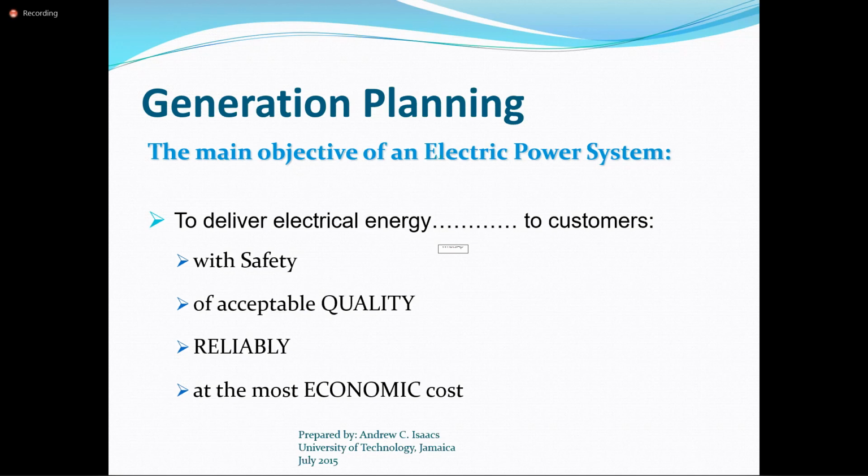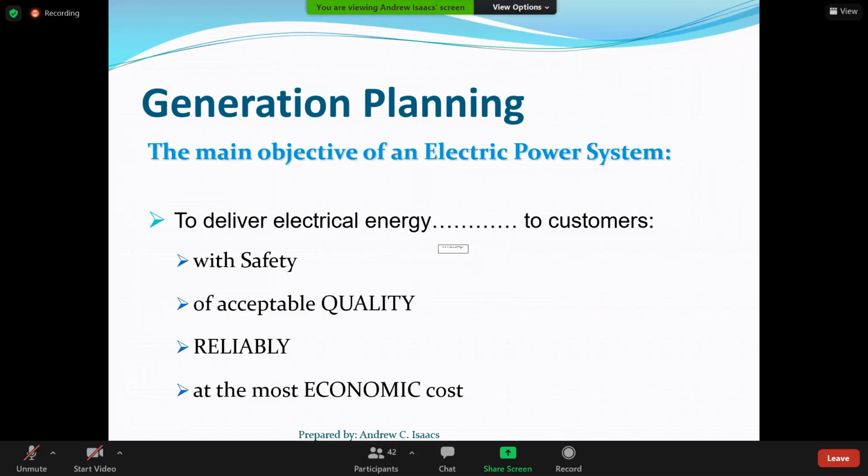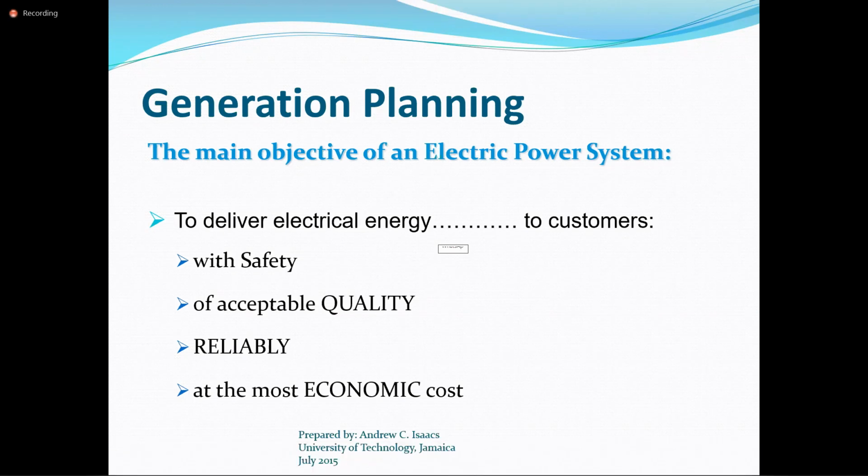And so if you have, for example, a stove with a clock that is supposed to be operating on 60 hertz, and you're trying to use that stove in the Jamaican system, which of course you all know by now is a 50 hertz system, and you are seeking to use the time on that stove to time your baking, then you're gonna have a problem. That is a clear issue where timing is concerned.